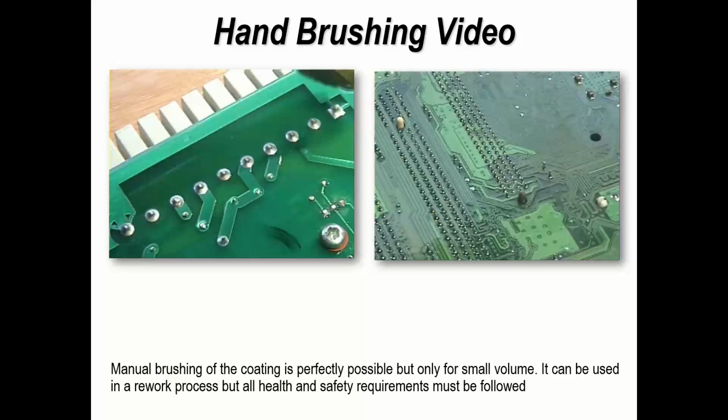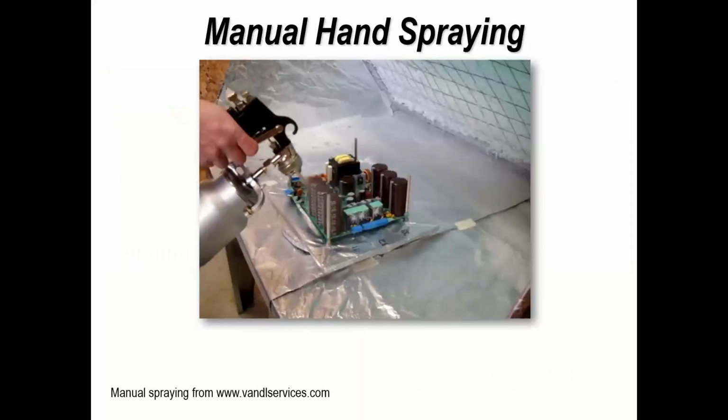And the material you use for a brush coating needs to be considered, because with most coatings having a solvent system, generally speaking, it evaporates. So when you're brushing, it's like painting a door on a hot day with thick paint. It will not tend to be very consistent when you're applying it. So again, if that's the operation you want to use, you need to speak to your supplier on the viscosity of the material being used.